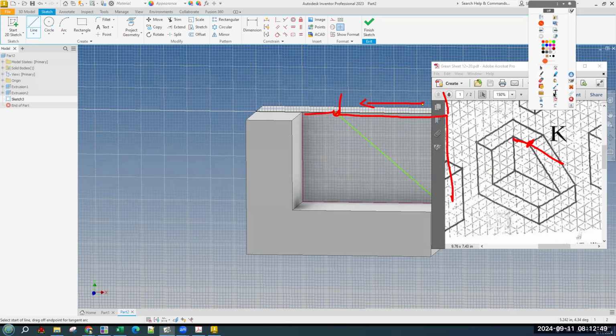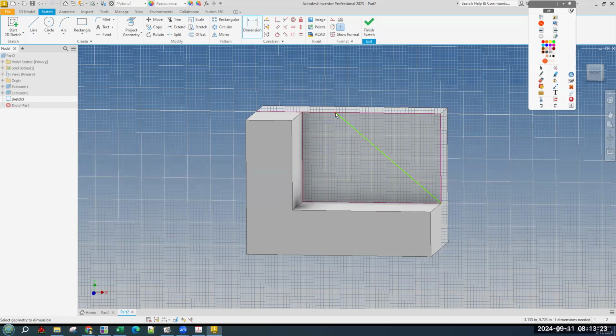It's the same thing. I think it's easier to read the isometric projections as what's left over, meaning when we're done, this will still be here. This other part won't, and it isn't there now on the shape. So we are just going to dimension the distance from this endpoint. First click, the second click is going to be this point right here. Because it's a dimension between 2 different things, it's the 3-click dimension. First click, second click, and then third click up here, and set it to 2.